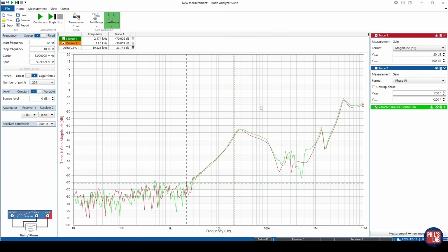But also in the higher frequency ranges with an altered input voltage magnitude, we can see the power supply rejection ratio has also changed. This could be due to derating of capacitors. It could be due to just changes of the overall system performance with a different input voltage. We might have better regulation in certain areas, but overall the trend is very, very similar. But keep in mind, your operating point does have an impact on the power supply rejection ratio.